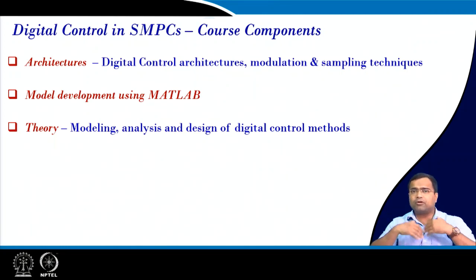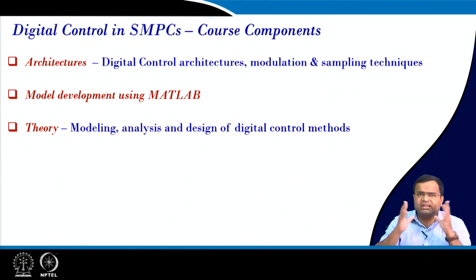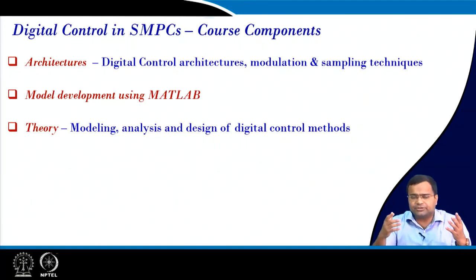So, we need to go for a fully discrete time model, but such a discrete time model may not be intuitive in terms of pole zero concepts and how they map to power stage parameters, which we can very easily visualize in the continuous time model. Such a discrete time model will have a lot of mathematical formulas and matrix exponentials, so you cannot visualize the pole zero or impedance effects so much, but it is very accurate.